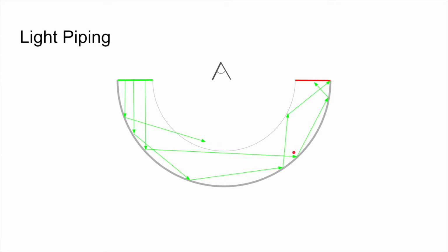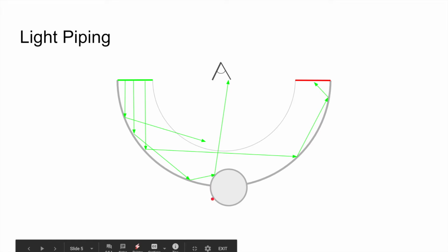Now, when you press an object into the soft surface, a ray's track will get interrupted, hit that part of the sensor, and then bounce out because it's greater than the TIR angle, and hit our camera. And then from the previous video, if you watched it, we can use the intensity of light at this pixel to estimate the actual gradient at that location.